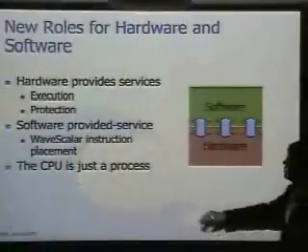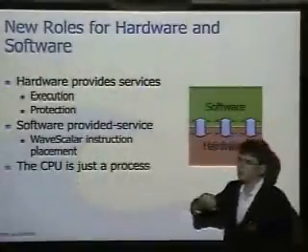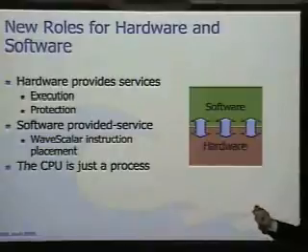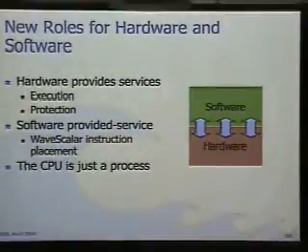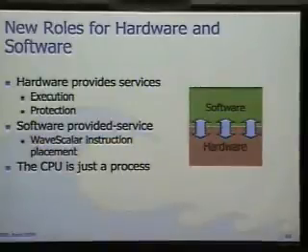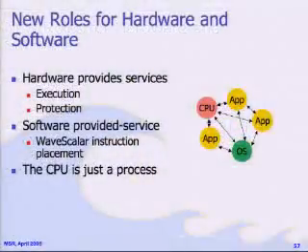So one instance of this in WaveScalar is the instruction placement scheme that I mentioned, where when we need to place the instruction, we actually trap to the firmware and have it tell us where that instruction should go. That removes a lot of complexity from the hardware and also makes that placement policy very, very flexible.